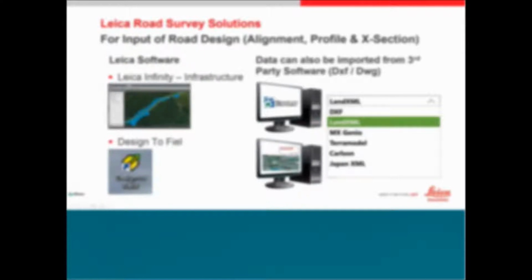For input on the desktop, we can use the Leica Infinity infrastructures module to create alignment and vertical profile, and then we can use Design to Field. Sorry, wrong spelling, missing a D. And then we can also import DXF files or LandXML or other formats from third-party software into Leica Infinity, and then convert into a format that our instrument can use.